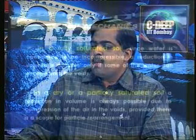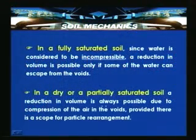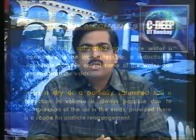In a dry or a partially saturated soil, a reduction in volume is always possible due to the compression of the air in the voids, provided there is a scope for particle rearrangement. That means that whether it is in a dense state or in a loose state, depending upon that, particle rearrangement will take place.